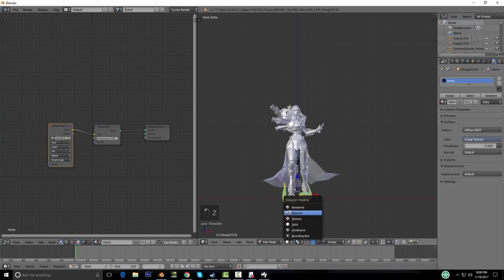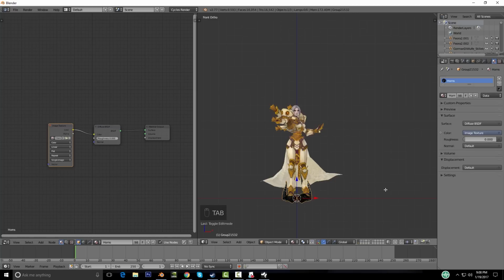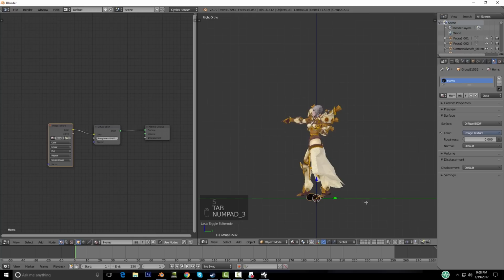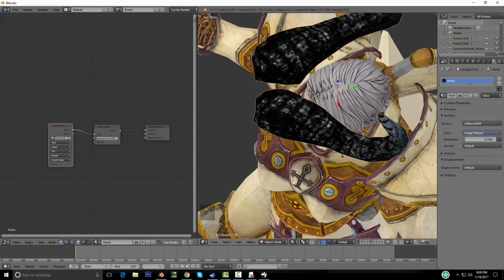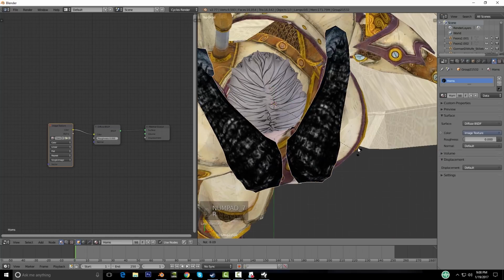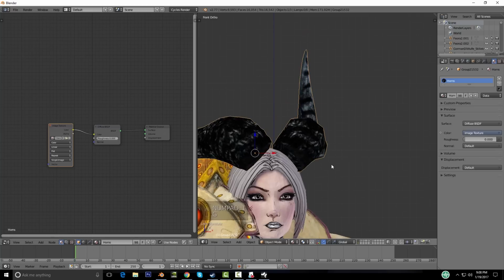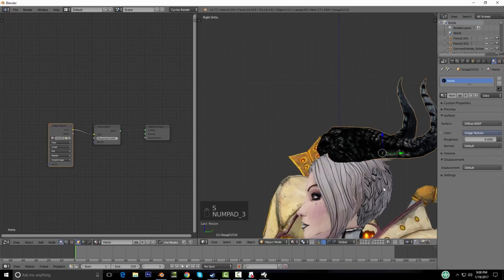I like to go into material just to make sure everything looks right. When I am on front view, I'm just going to hit R again to rotate a little bit, try to get them kind of even. And there we go. Going to scale it down just a little bit. And now we can grab it on the Z axis, bring it up here, hitting period in order to zoom in. And now we'll just kind of tweak and move, and we're just trying to get it right where we want it. I'm going to scale it down a little bit more. Typically, you don't want to...